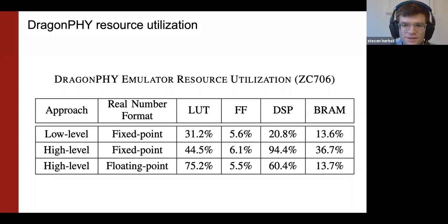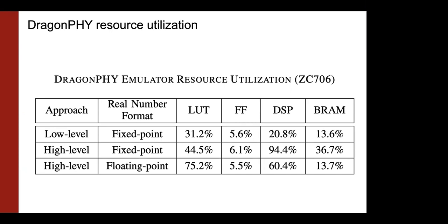Yeah, I think it's definitely an interesting area, because it's a little bit counterintuitive. When you're looking at direct logic analyzer traces from an FPGA, the emulator clock is always running at a fixed frequency, but it's representing something which has no connection to that frequency. The traditional emulators run at either a fraction of real time or some multiple of real time, whereas in this case there's a separation between the physical time taken by the clock on the FPGA versus the thing that it's modeling. It took some time to wrap my head around that and build some debugging tools to better understand what's happening.